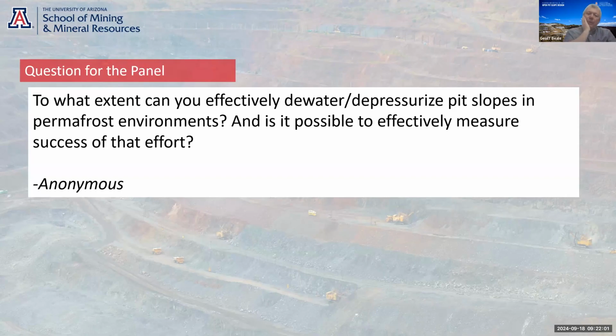Yeah, so there's a lot of experience of this at Red Dog, in the diamond mines in Northwest Territories in Canada, and also at some of the large open pits in Russia. If you're in the permafrost zone, then obviously you've got more rock strength as well, and so often you don't need to depressurize permafrost because it's inherently stronger because of the ice. There are a couple of sites I've worked on in Canada and one in Russia where we've put thermistors in behind the wall to measure the freeze back. If you expose the pit wall, particularly north-facing pit walls in the northern hemisphere, it actually cools down after you've mined through it, so it makes the rock stronger.